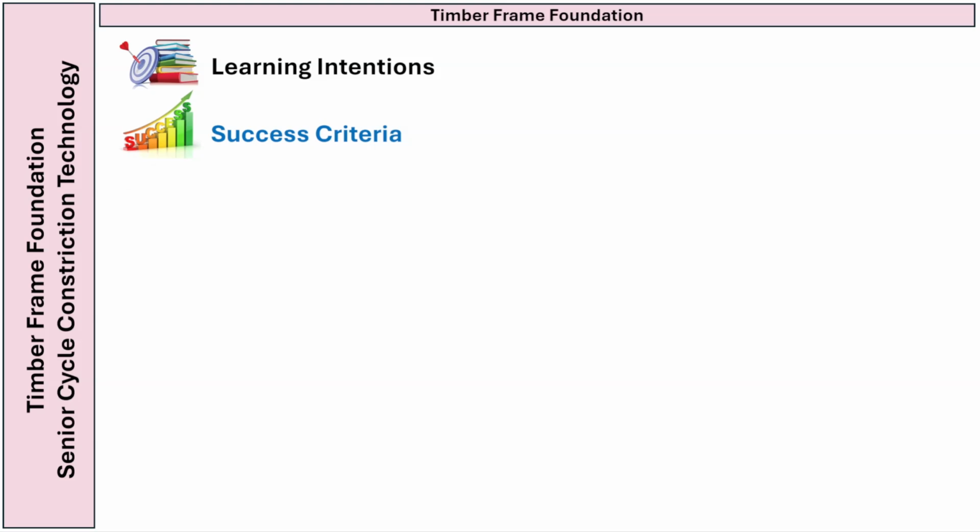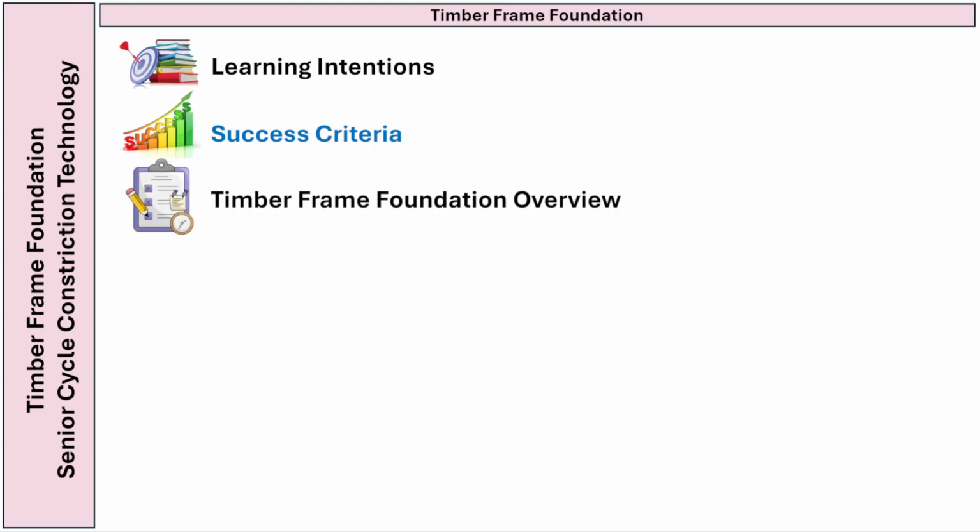the detail. A timber frame foundation is very similar in layout to a strip foundation, but the wall structure above it is made of timber panels instead of concrete blocks. The foundation itself is still a concrete strip foundation, but the wall that sits on top is a timber frame wall, usually supported on a sole plate and bottom rail to keep the timber above ground level and protected from moisture. One main advantage of the timber frame construction is that it's lightweight and quicker to build, with much of the structure prefabricated off-site. It also has excellent insulation potential, which helps reduce energy use when properly insulated.